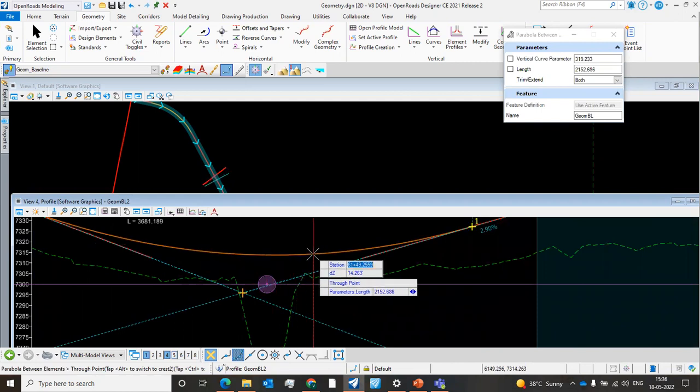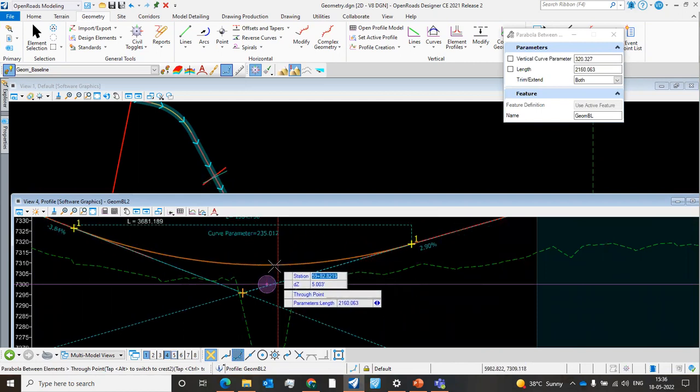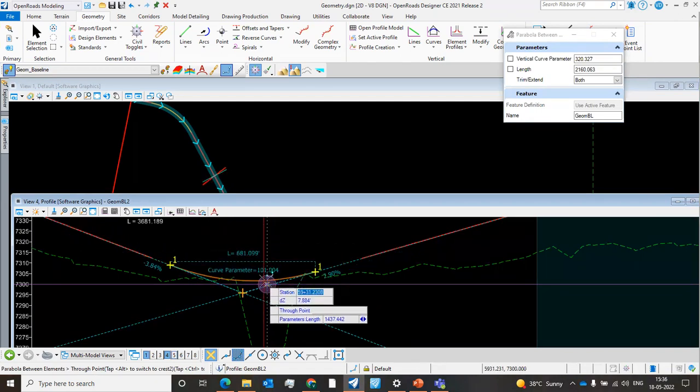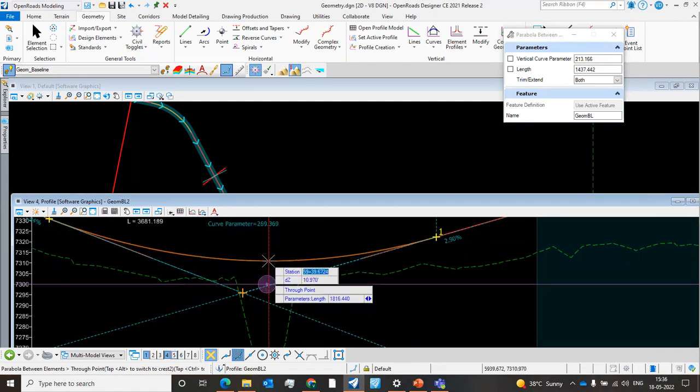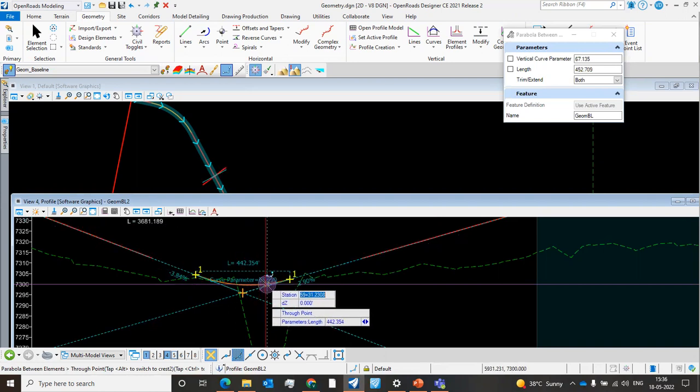The civil Accudraw, the purple color circle, is now fixed at that location. So that is our zero. That point is our zero. And as I move further, it will maintain a distance of 10, 20, whatever we want. So now I'll toggle, I'll give a chainage of 59, let's say 59.30, 59 plus 31.